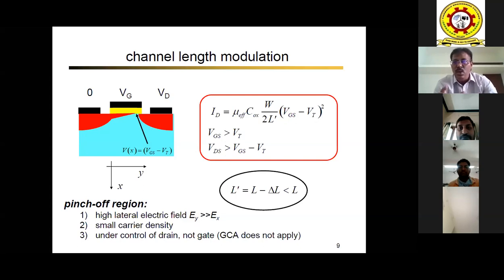Now, when the channel is becoming too short, we no longer say it is controlled by only the VDS. Now you see on the y-axis we see the VDS, that is what we call the voltage connected between the drain and the source. And on the X, there is one more coming here, right? That is your gate voltage. Okay, now you can ask one question: why is it that gate voltage was also there earlier, right? Now why are you calling it two-dimensional fields? As the channel is becoming lower and lower and reduced to a short channel level, your gate level also has a predominant effect on the movement of your carriers. That's why it has become two-dimensional when you're reducing the channel length.